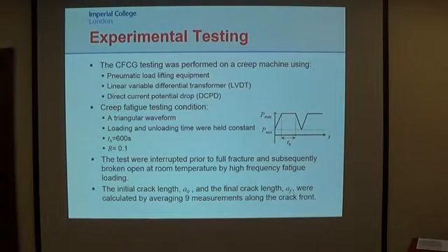And the hold time of 600 seconds is superimposed on the maximum load. And the load ratio R of 0.1 is used. So the tests were interrupted before the full fracture and subsequently broken open by the high frequency fatigue loading. So the initial and the final crack length is calculated by averaging the 9 measurements along the crack front.